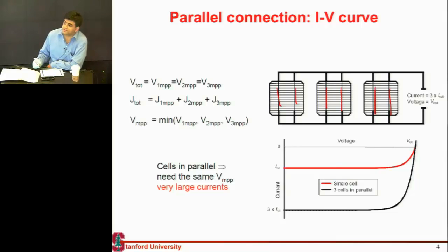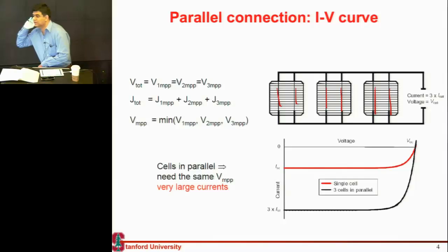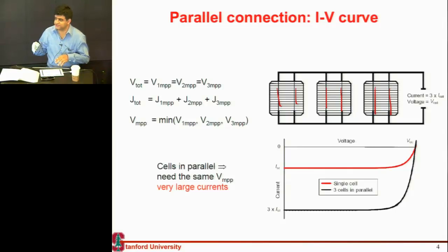Sorry, can you repeat that? So one thing is that if you have too much current and a narrow bus bar, then you'll have a lot of I square R loss. But I could make a wider bus bar instead of making 2, right, to minimize that same resistive loss.